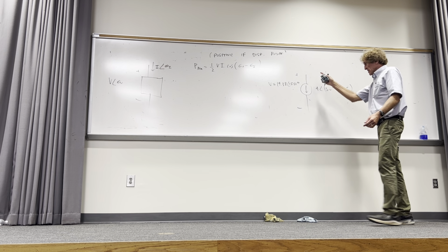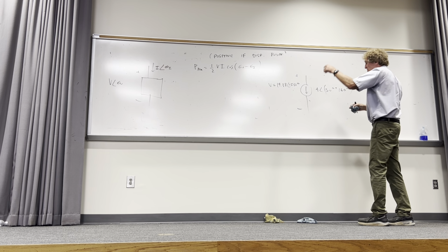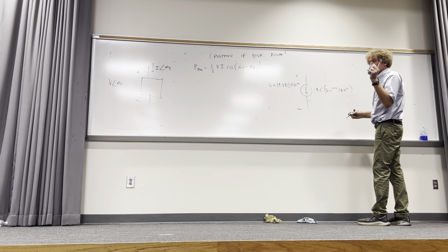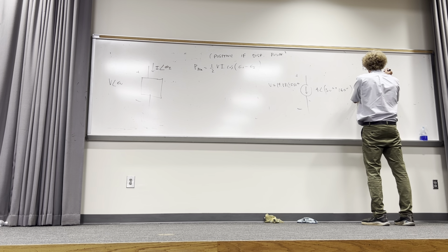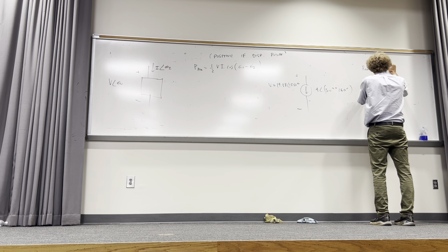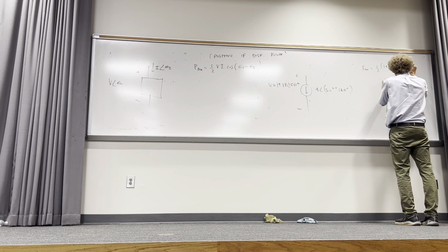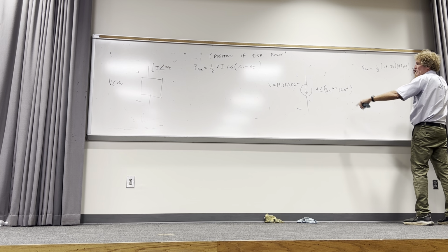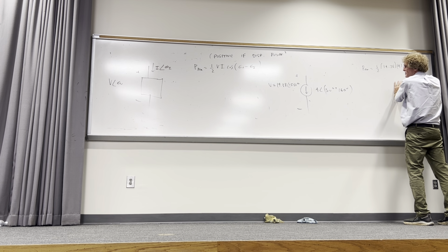So now I'm saying, I got the current going that way, now I can use that equation to find the power. Now please watch this. So the power associated with that, and if it's negative, it's supplying it. That average power would be equal to 1/2 times V, which is going to be 14.38, and then times I, which is 4, and then times the cosine of theta V, well, that's 15.52, pardon me.